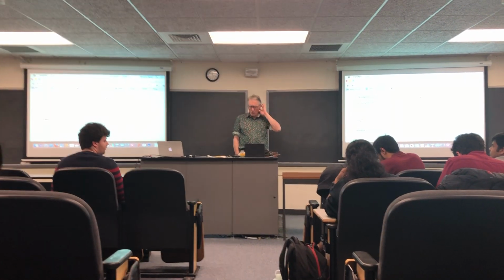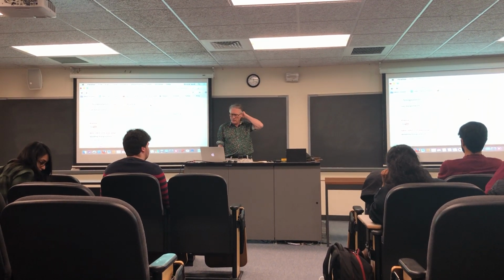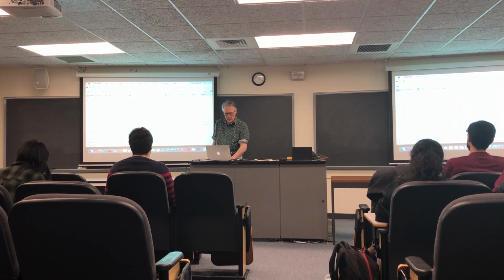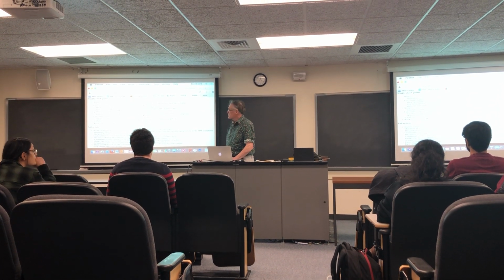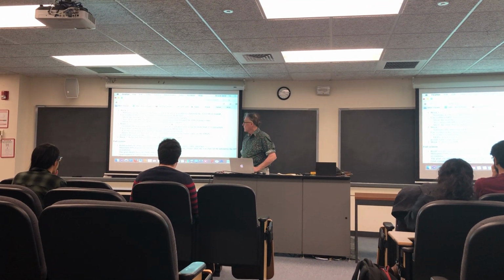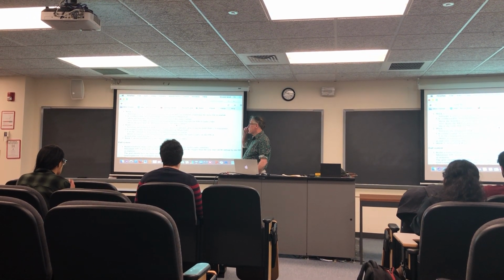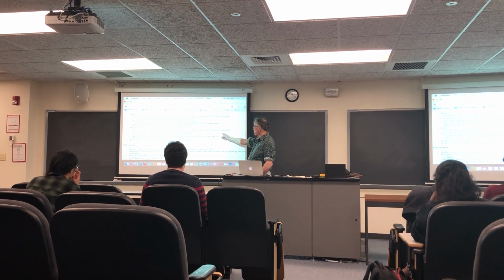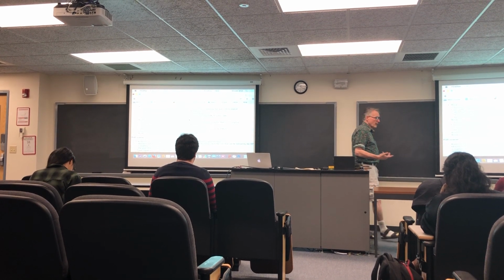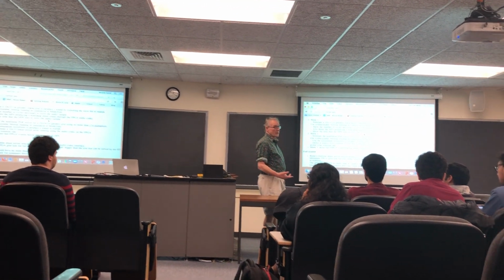We're now in week 2 of lab exercise 2. And the checkpoint for this week is to simulate the solver for a 24 by 24 or greater grid using no more than 174 multipliers. That's to simulate what the environment you're going to have on the FPGA. There's 174 18-bit multipliers.